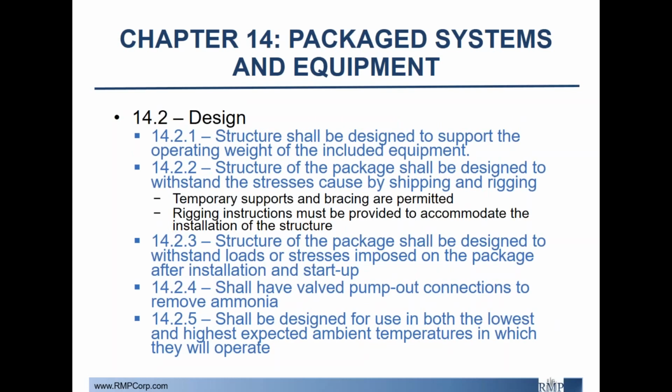So the design of package systems is very important. Structure shall be designed to support the operating weight of included equipment, and the structure shall be designed to withstand stresses caused by shipping, rigging, and operating. Temporary supports are permitted, and rigging instructions must always be provided by the manufacturer. Structure of the package shall also be designed to withstand loads or stresses imposed after installation and startup. They should always have a valve pump out connection to remove ammonia.